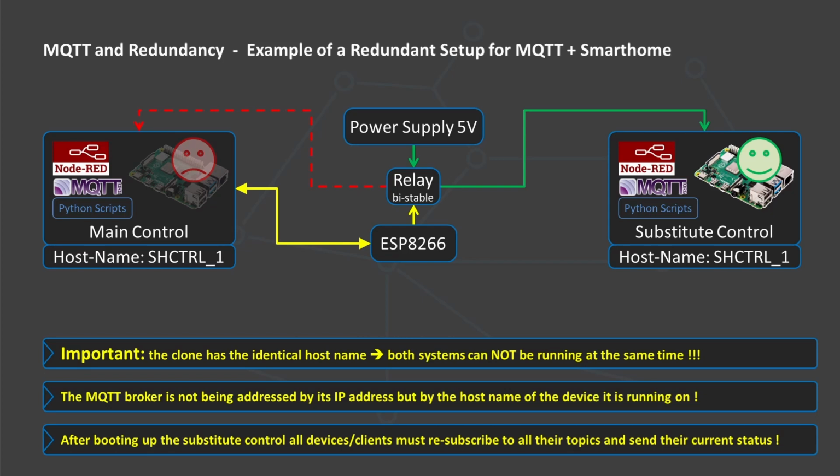Testing new functions or algorithms is being done on another Raspberry Pi. Using MQTT, I have full access to any signal, command or interface, even from that additional Raspberry, which makes testing new functions so easy without risking messing up the main control. That's why it might not even be necessary to create full redundancy for the entire home automation control system. Some sort of simplified emergency functionality on a third device might be fully sufficient, and a piece of cake by strictly using MQTT.